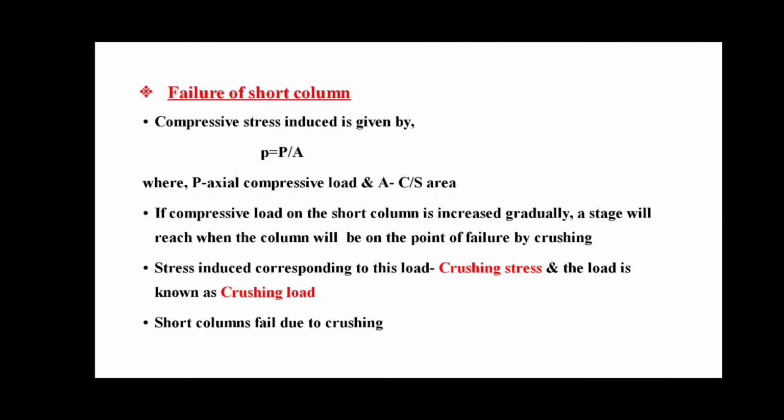If the compressive load on the short column is increased gradually, a stage will be reached when the column will be on the point of failure by crushing. The stress induced corresponding to this load is known as the crushing stress, and that load is known as the crushing load. And the short column fails due to crushing. So, that is the failure of a short column. That is, if the compressive load on the short column is gradually increased, a point will be reached where the column fails by crushing, and we can say that the short column fails due to crushing.